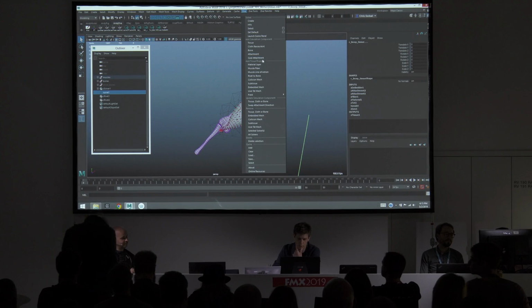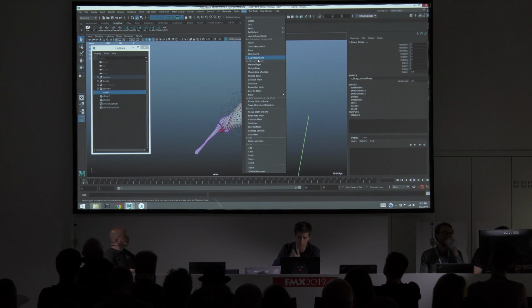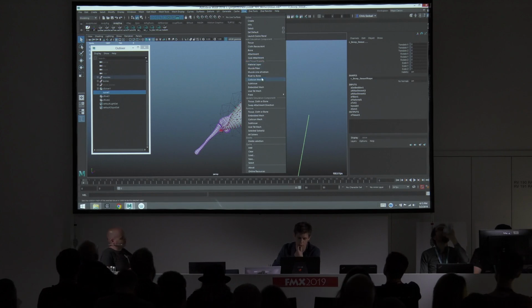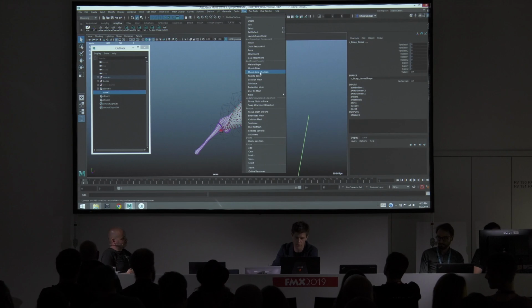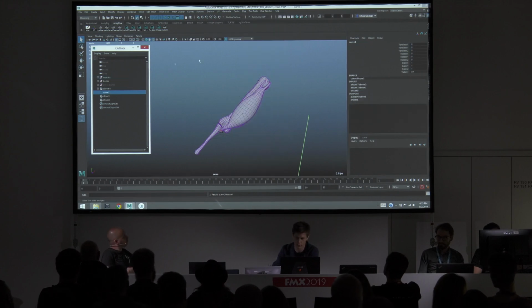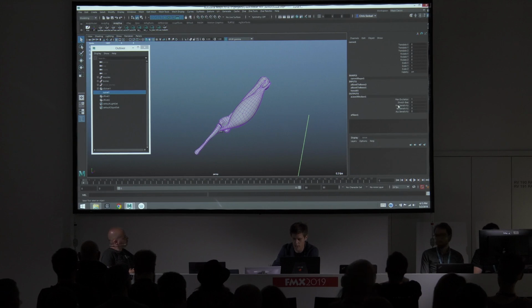And the mechanism we use to compute how much firing needs to happen is called line of action or muscle line of action. So with those two objects selected and I choose muscle line of action, you'll see that we get this line of action node here now. So you can choose to fire the muscles based on position here. So this is position of the endpoints.